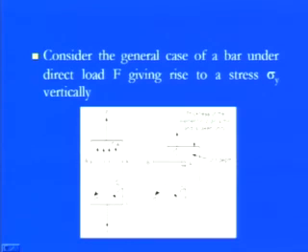So now if you see this, we found that due to the force component in the y direction, we have tensile pulling, the tensile forces are there, and due to these tensile forces we have tensile stresses in the y direction only. So we have the sigma y. Sigma y is nothing but, if you consider this section BA, equal to the applied force divided by the area.